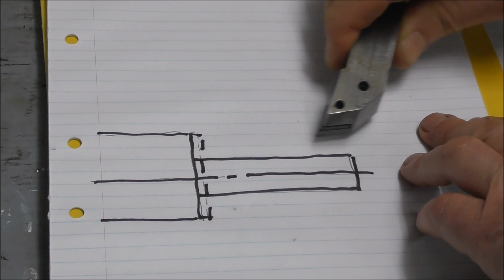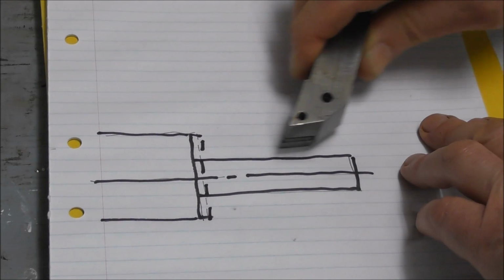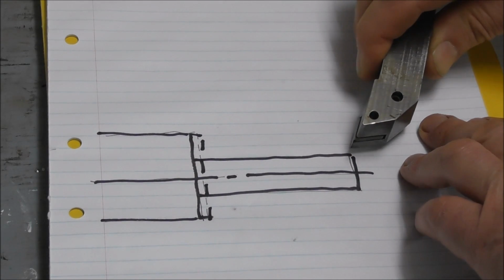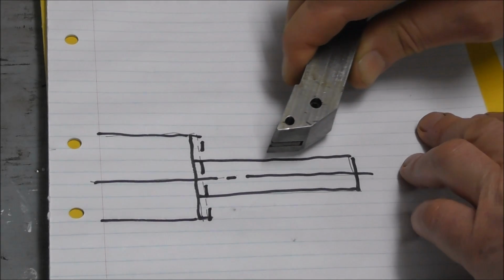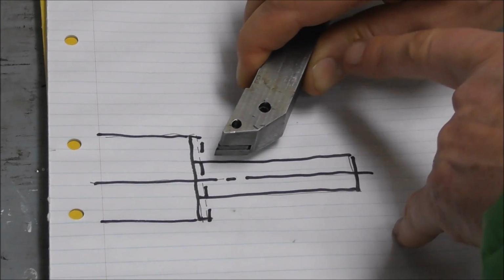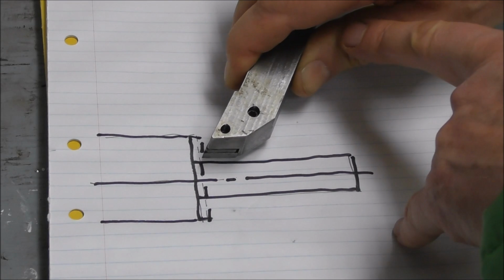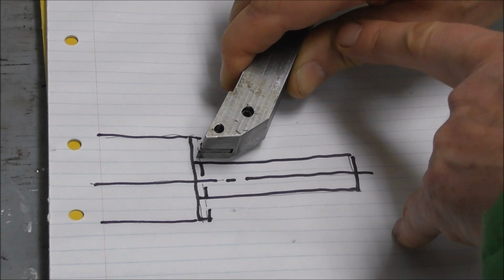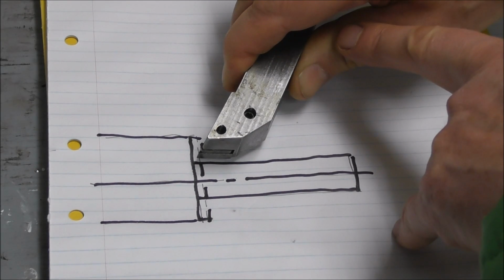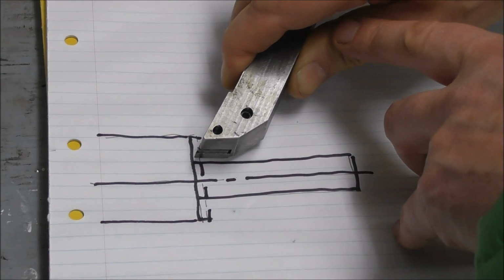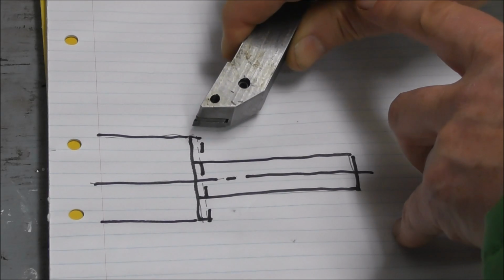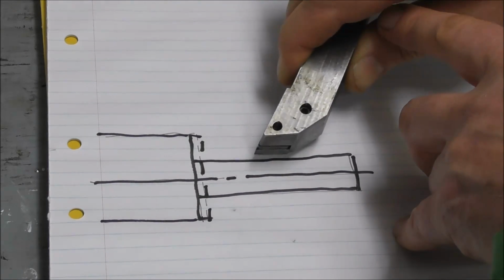So you would take cut 1, cut 2, and then finally when you come to the finishing pass, because it's on such a steep angle, it can more comfortably go in the whole depth of the finishing cut. If it was aluminium or acetal or something soft, you could almost get away with that and then come back in for the finishing cut, or come back in.